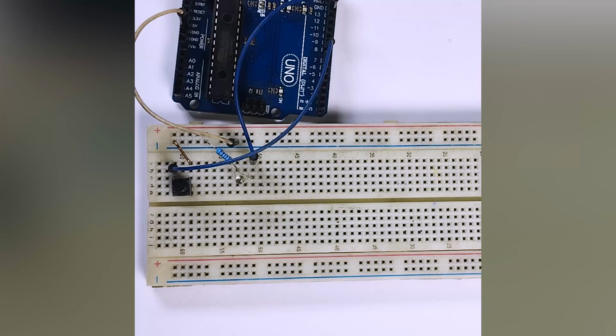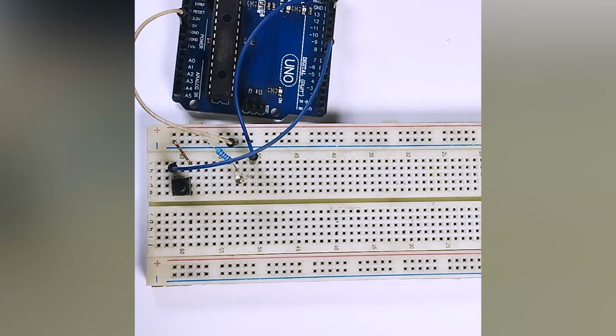Now when we have pins declared as input, it means we are not assigning them a high value or a low value. They're just supposed to sit and wait for signals, sense them, and then the microcontroller can carry out a function once it senses this signal. But if we leave them floating, that is, leaving them without a known voltage level, they can take up a random voltage level from electrical noise and other sources.